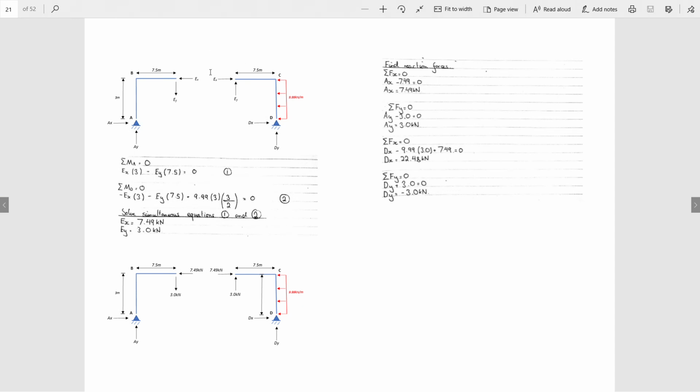Right, so we're breaking that down into 2 segments. Just put a little fake line in the air here. So from this, we've got both our segments and working out EX and EY about that broken about point. Very simple, moment about A, moment about D, and we're left with 2 equations, our unknowns EX, EY, and then substituting EX and EY as A and B, I then solved these equations in 4 different simultaneous equation calculators just to compare the values and spat out both these values. And more specifically, the value of EY is 2.997. Right, so we sub in the values.